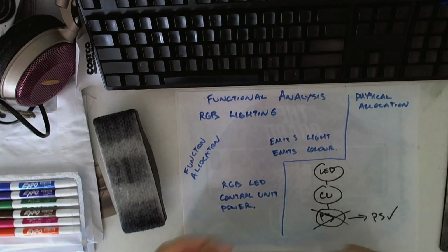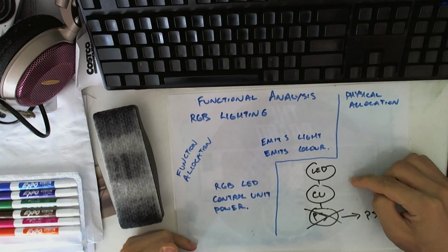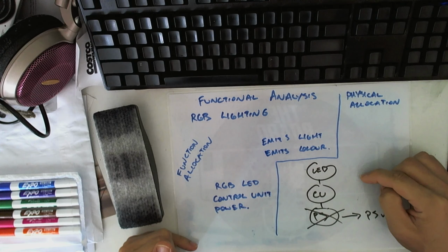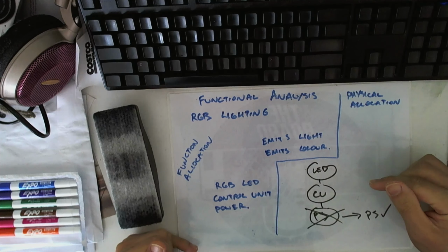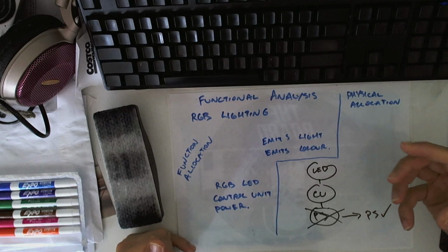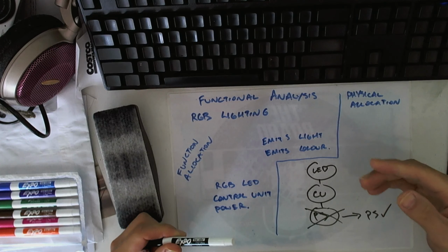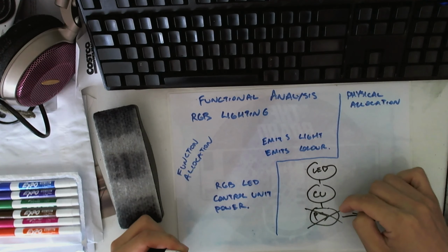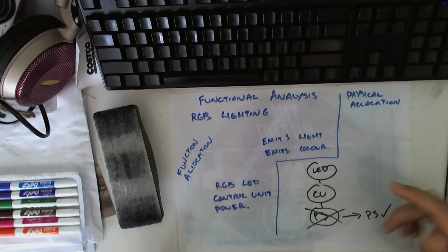For most consumer goods, they will put this physical allocation down to the lowest cost-effective level. For goods that tend to be at a higher spec, so things that have very good warranty, or they're designed to last for very long, or they're designed to have very low maintenance, they will be designed in a particular fashion that will allow a technician or a maintainer or a service guy to come along and check components individually and then either remove and replace or repair. And it may be a repair matter. Is it easier to repair a power supply all by itself or a power supply that's integrated with your control unit? I don't know, and it comes down to your design.